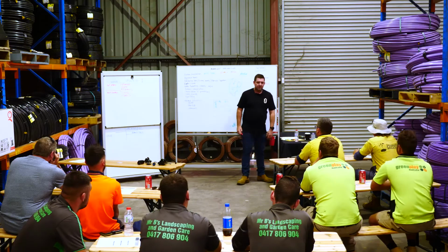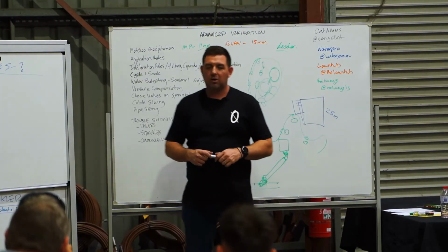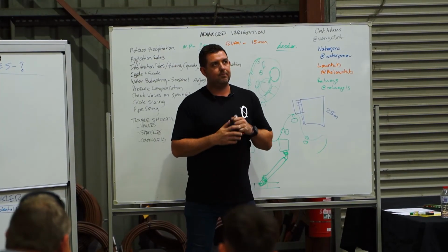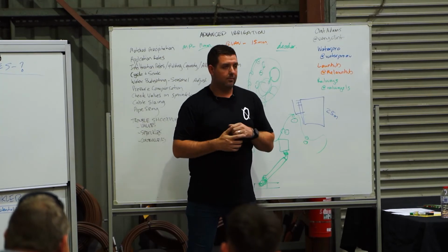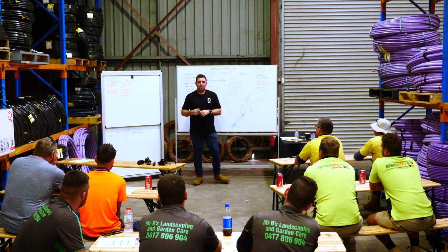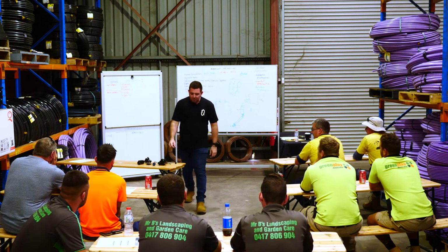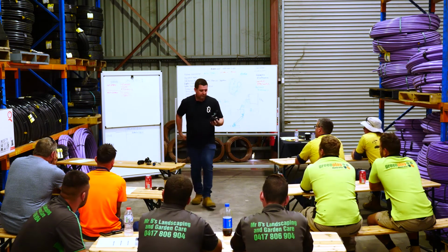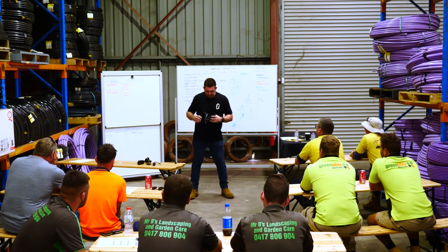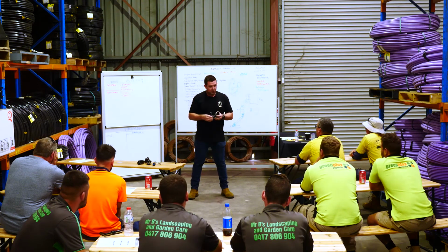Any other things you guys can think of? I think that's it. It's really not opening or not closing. Not getting enough water, that's probably the last one. So the flow control, we talked about it yesterday. Sometimes you'll buy a valve off the shelf and the person that's worked in the shop has been standing there talking to someone and they're just playing with this and they've turned that down. So that there, what I'm screwing down now is the flow control.